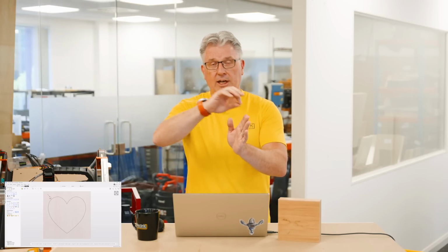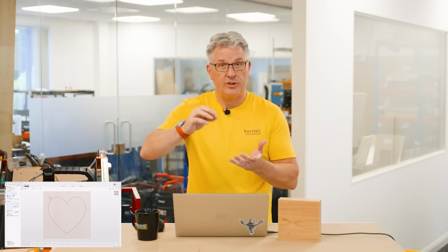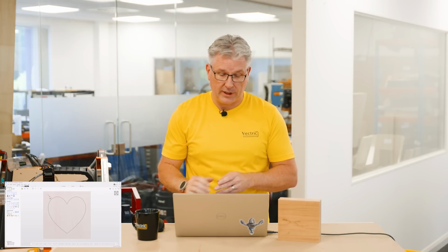The beauty of the Moulding Toolpath is it doesn't actually create a 3D component. It will actually use that cross section to define the cutting path of your tool. And it makes for a really quick, very accurate toolpath. And with some of the features that we've added in, you can do a much better job actually than using a 3D component. So if you can use the Moulding Toolpath, it's fast, it's efficient, and you're going to get a better end result, a better surface finish, because you're not doing a raster cut, you're actually following that curve. So it does turn out to be really quite nice.